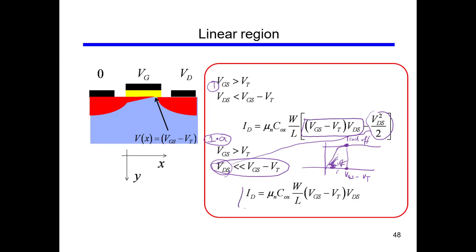That's why in the linear region you have this equation, and this is the same equation that we saw earlier when we dealt with the linear region separately. So you see that the equation in the triode region that we derived in this lecture is very generic. From that you can reduce to the saturation equation and also the equation for the linear region.